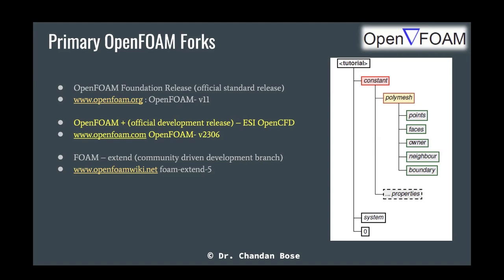So as you said correctly, if you go to the zero folder for any basic incompressible flow problem, you will see two files. One is pressure, another is velocity. And if you open those pressure and velocity files, I'll show you, they will have the boundary names that you have created in your mesh, and then the corresponding boundary conditions. And also at t equal to 0, how do you want to initialize the problem? Now the next folder is constant, right?